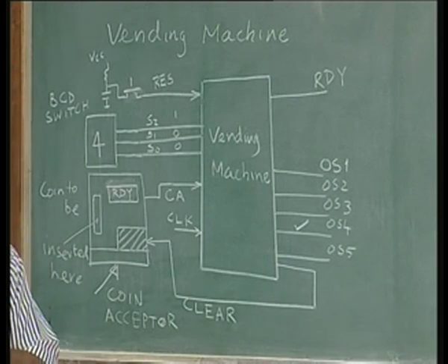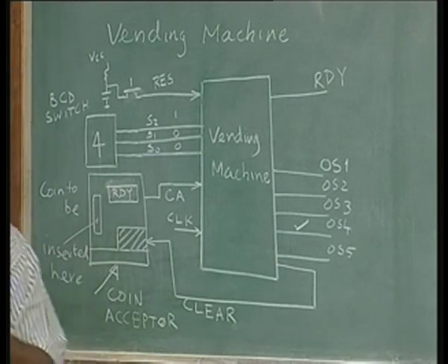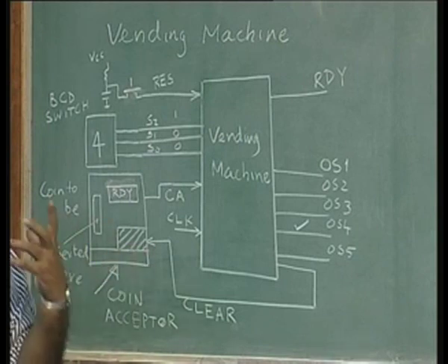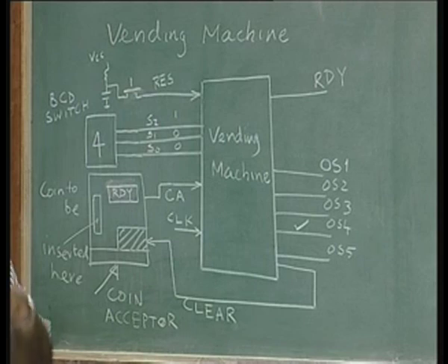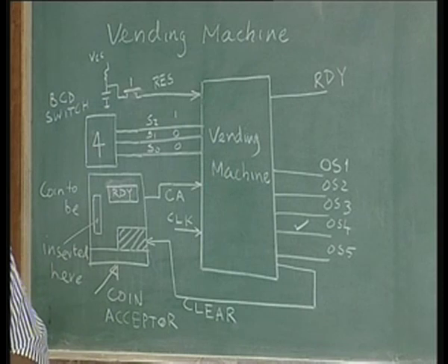You need a 555 timer. All of you are familiar with 555 timers. 555 timers require large capacitors for low frequencies, and also low frequency waveforms are generally not stable. Very difficult to have a very stable waveform at low frequencies.